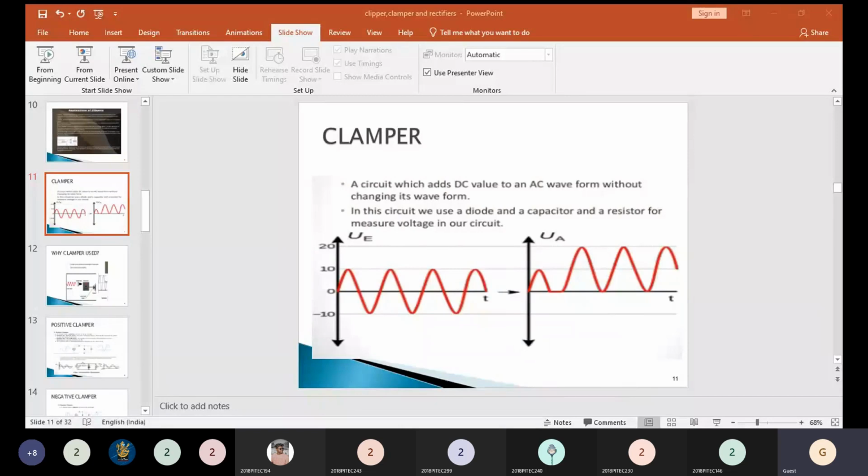So what is your Im? Two resistances are involved, the same as in the second question we discussed. The same formula is repeated here. We have two resistors, the forward resistance and the load resistance, connected in series. Series means you should add the two resistance values. By Ohm's law, I is equal to V by R, so Im is equal to Vm divided by Rf plus RL. Just substitute Rf and RL, 25 plus 800.